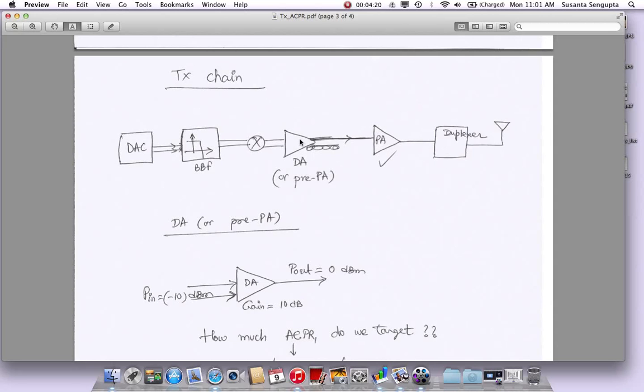If you put signals to it, they're going to have their second order distortion, third order distortion, fourth order, fifth order, and so on. Typically, if you process in differential mode, then you don't have so much second order distortion. That is your assumption, which is true most of the time. But sometimes the second order distortion could also come up if the swings are too large and the system starts to get saturated. Still, let's assume the second order distortion is not much. You don't have so much of even order harmonics, but odd order distortions are there, more like third and fifth.